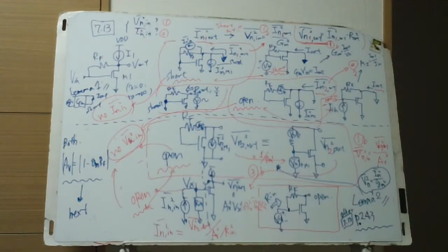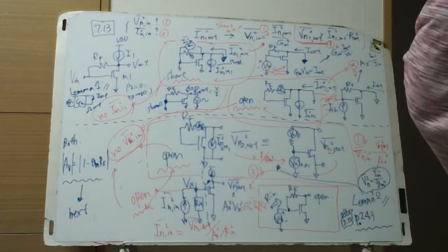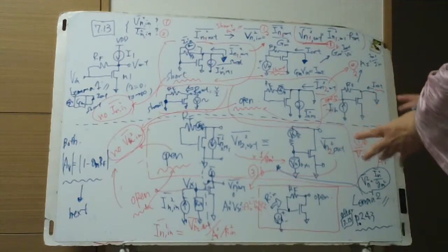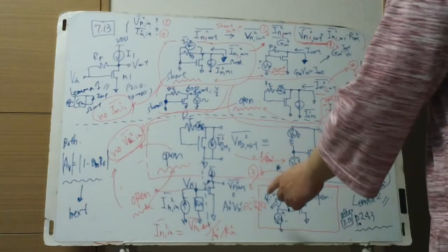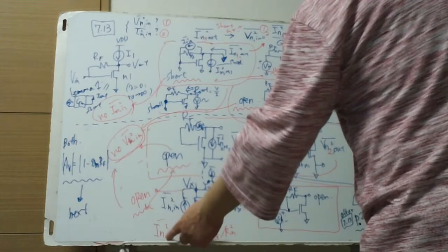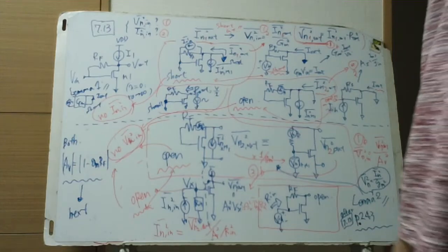Because we have the open circuit output, the open circuit gain. That must be considered. The point is that it has to be considered. Okay, leaving this difference aside, we need to get the input referred noise In in squared bar, and this is open.